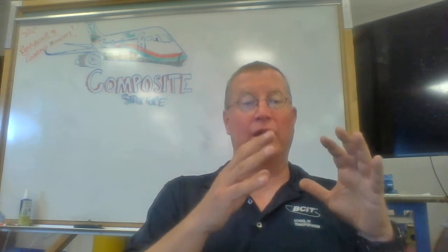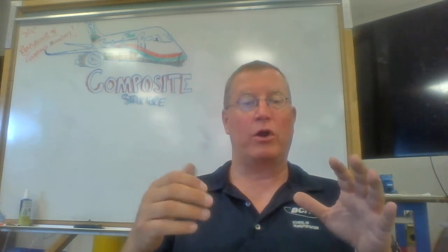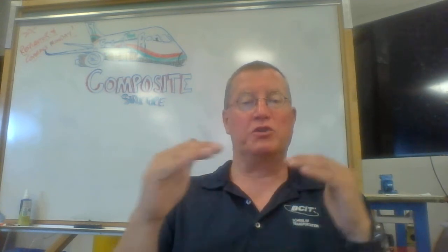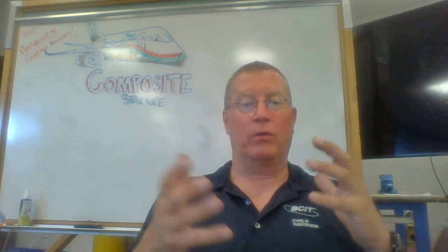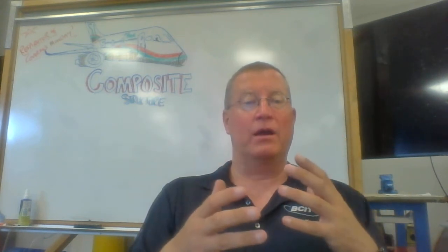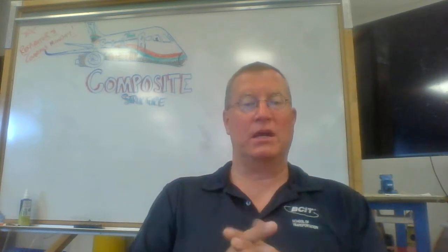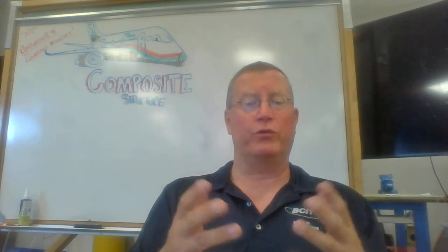That feedback will then control the box to cycle power on and off to our heating pad in order to maintain a very tight temperature range, right? All the time we'll have vacuum provided and some sort of feedback from that vacuum to make sure that we're maintaining vacuum within the area of the repair, right? So a very useful tool.